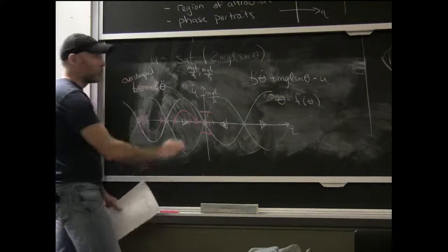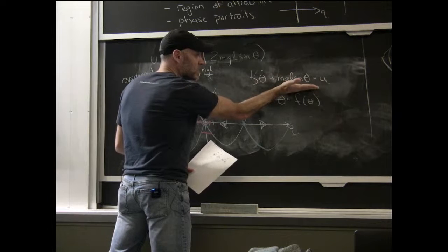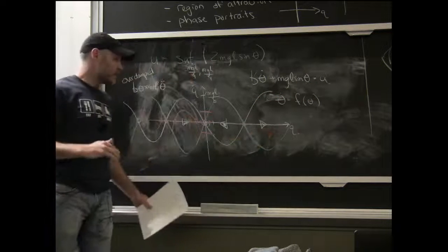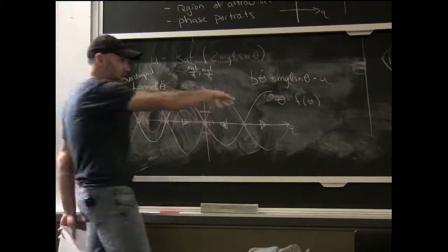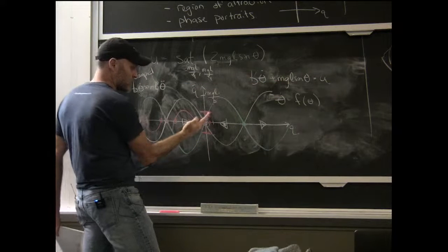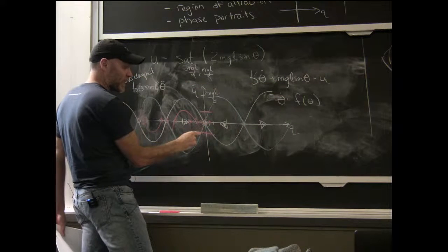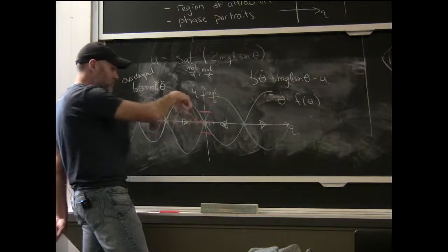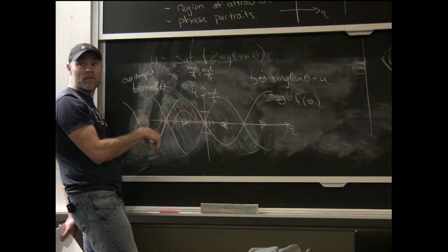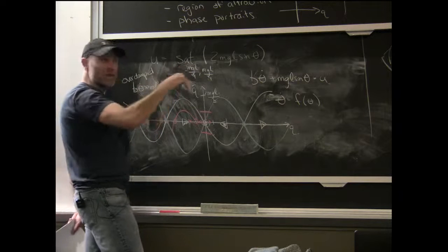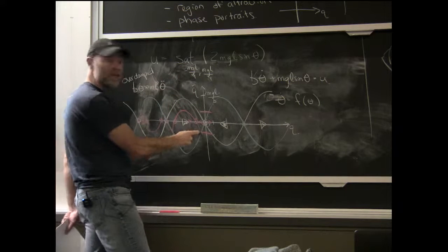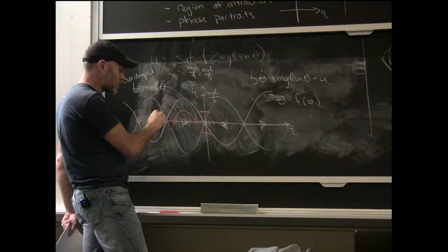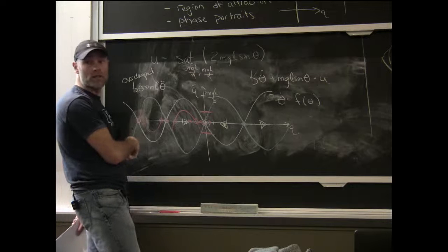And how does the saturation of the motor play into that as well? So when I look at the equations that I get, when I insert this saturated controller in, then they are no longer smooth. I get a set of equations that is smooth here, but then when I hit the discontinuity, the dynamics look like the pendulum dynamics just shifted down. So every time you hit that saturation, you have possibly a kink in the plot, okay? But we can do the graphical analysis to see all of that.